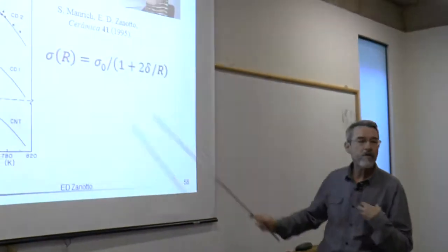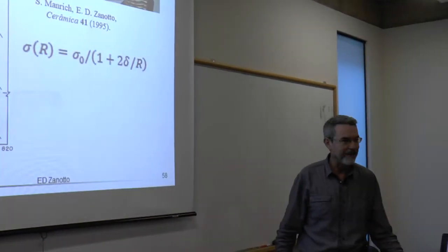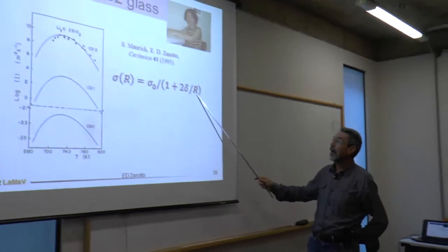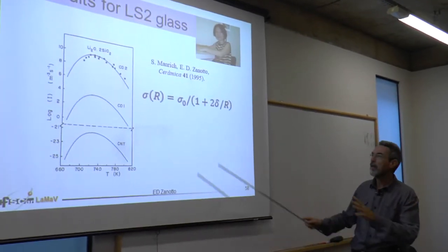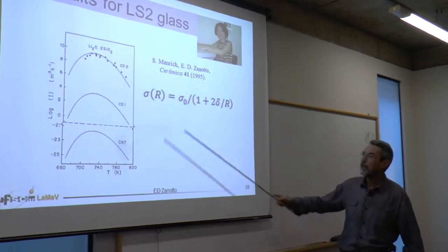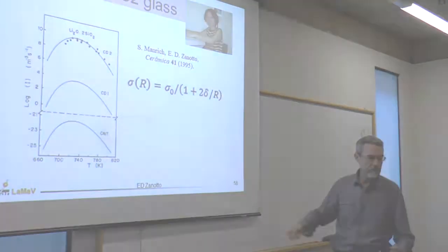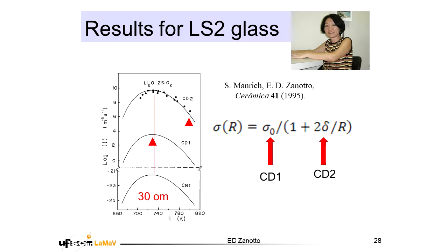It has some thickness, as if you recall, I have shown this in my first lecture on the molecular dynamics simulation results for supercooled germanium. They were able to measure the thickness of the interface. This is delta. Of course, you cannot measure this parameter experimentally, but it's a parameter there. You know, how diffuse is this interface, and R is the radius, considering a spherical nucleus. Anyway, there are several equations which relate the surface energy to the size of the particle. This is one of them, called the Thomson equation.